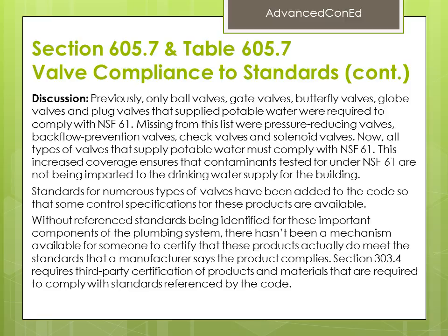Section 605.7 and Table 605.7. Valve compliance to standards, continued. Discussion. Previously, only ball valves, gate valves, butterfly valves, globe valves, and plug valves that supplied potable water were required to comply with NSF 61. Missing from this list were pressure-reducing valves, backflow prevention valves, check valves, and solenoid valves. Now, all types of valves that supply potable water must comply with NSF 61.